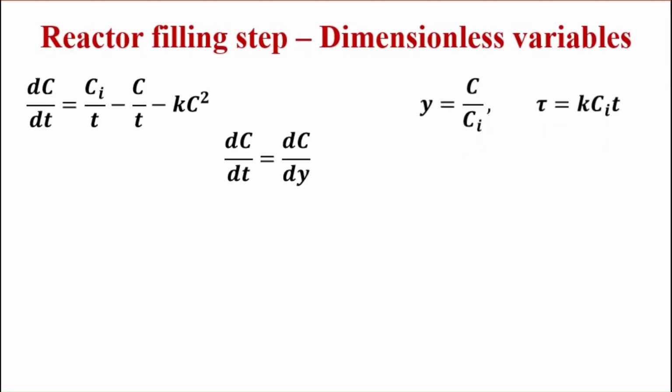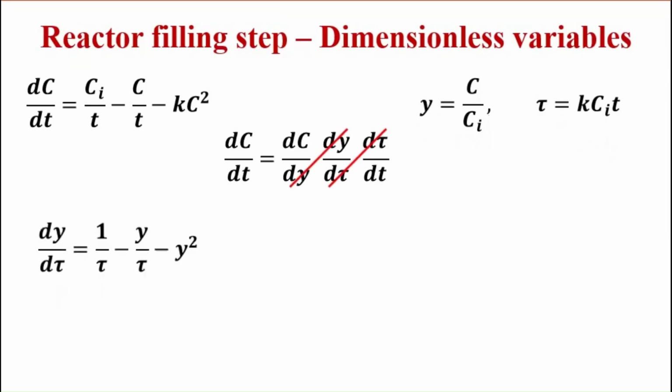significance in chemical engineering. To convert this differential equation to a dimensionless form, a suitable change of variables is introduced and the chain rule is applied. As a result, the governing equation for the concentration distribution in the reactor is transformed into a dimensionless differential equation that contains only a single dimensionless parameter, the Damkohler number. The Damkohler number is one of the main parameters in the design of chemical reactors.